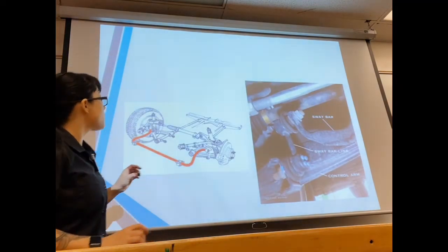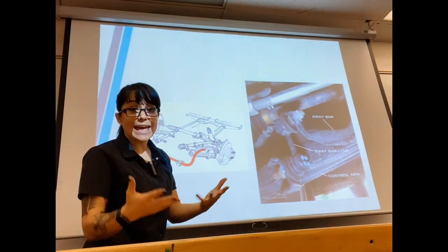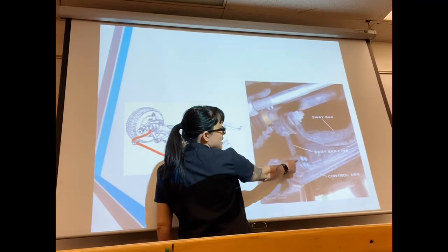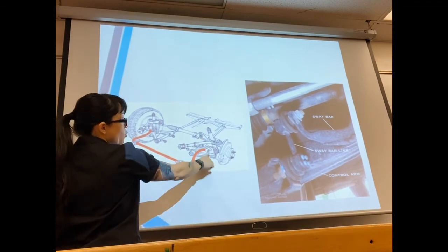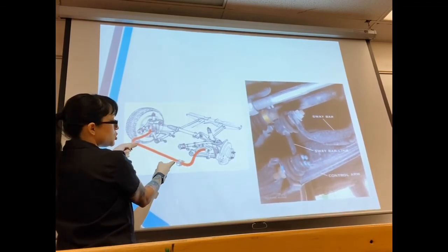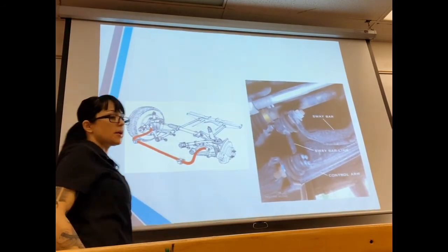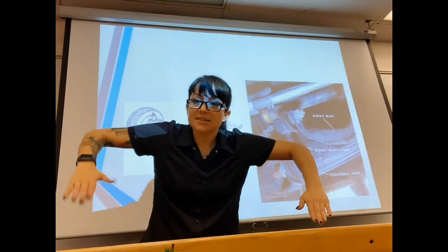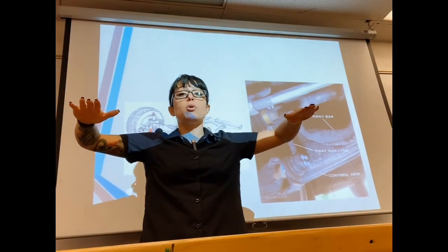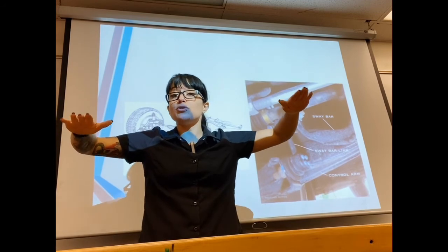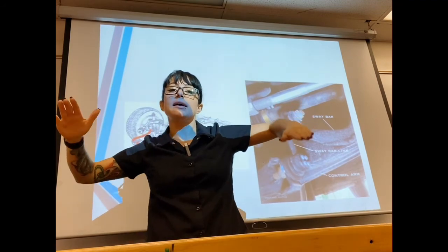If we're looking at a sway bar here, usually we're going to have a sway bar and they're going to include end links. If we get a closer look here, we've got these tiny little links that either have bushings or little ball joints in them. And that sway bar is going to attach from one lower control arm. I'm going to have two bushings that attach to the frame here, and it's going to attach to the other side's control arm. So essentially your sway bar looks like this. This side's attached to this lower control arm, this side's attached to this lower control arm, and when you go through a turn to transfer body weight, you get almost a torsion action of your sway bar, and it's going to transfer load from one side to the other.